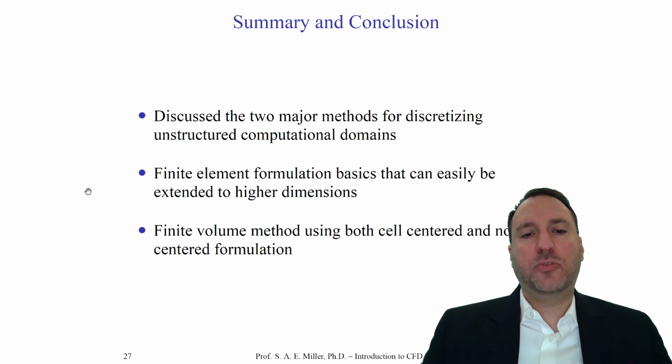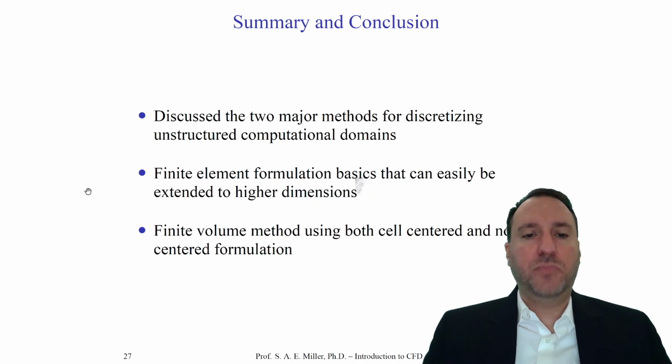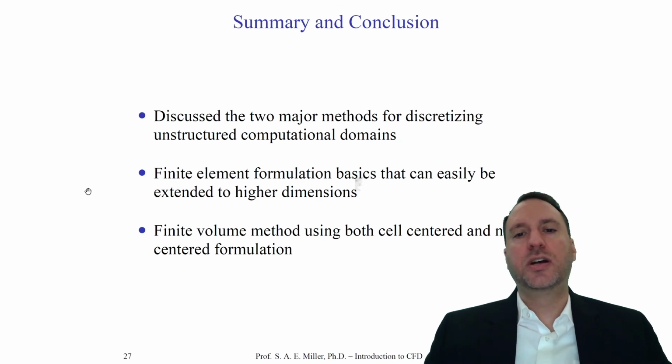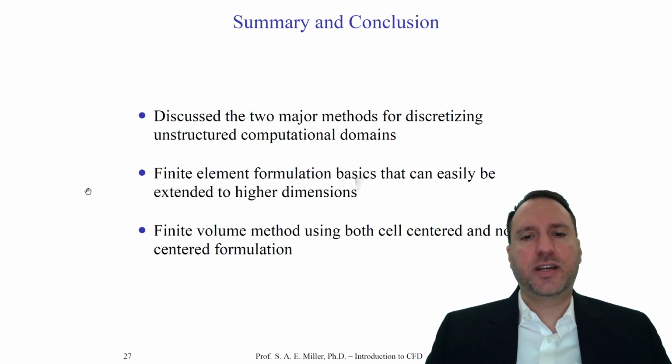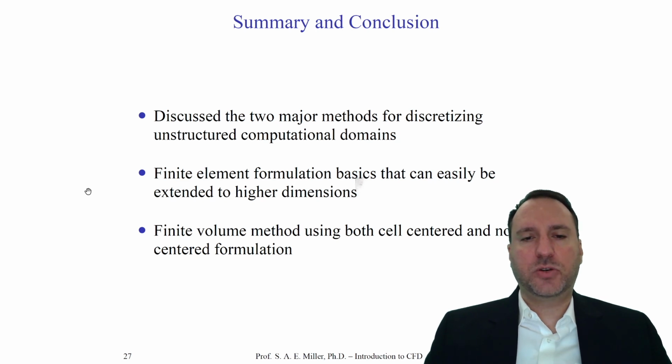In fact, the finite element formulation can easily find the highest order of accuracy solutions than any other approach because, of course, all your basis functions are local to a node. If you wanted to find a high order solution with a finite difference approach, then you would have very, very large stencils. For example, a 40th or 50th order accurate approach might use a stencil of anywhere from like 75 to 100 grid points. That's humongous and not practical, but has been done in research. That's why the finite element approach is so favorable today, because it can handle very high order of accuracy and find solutions that way without extensively complex finite difference approaches.